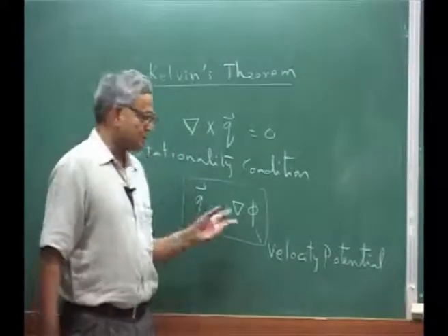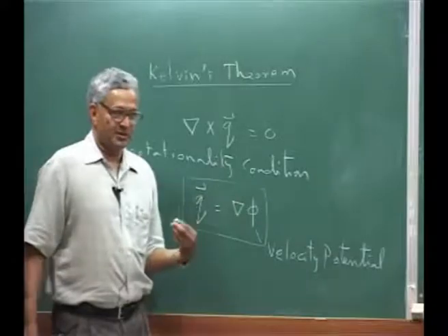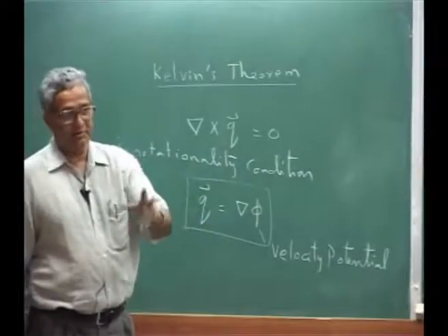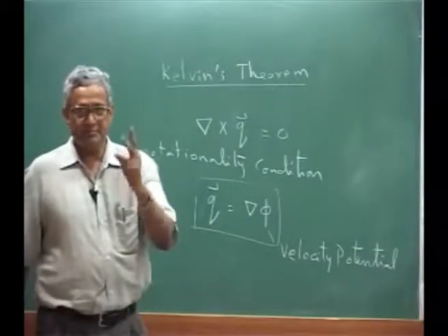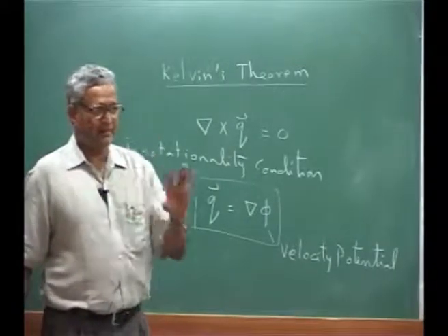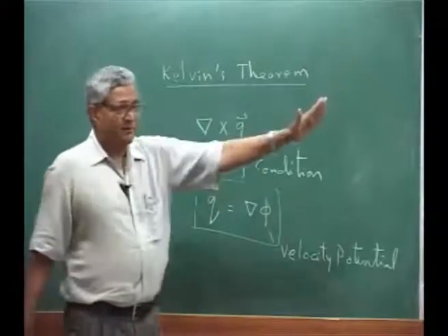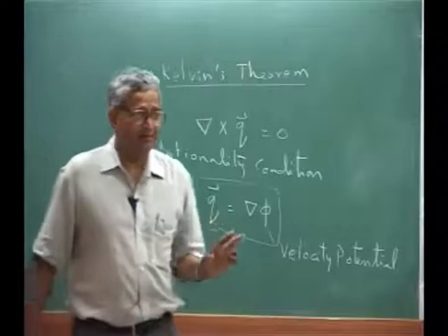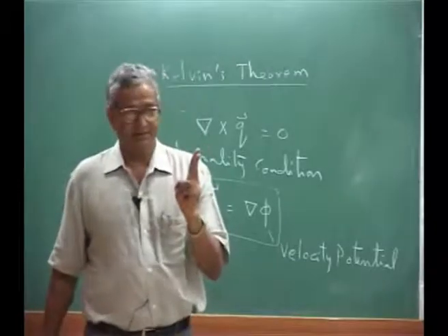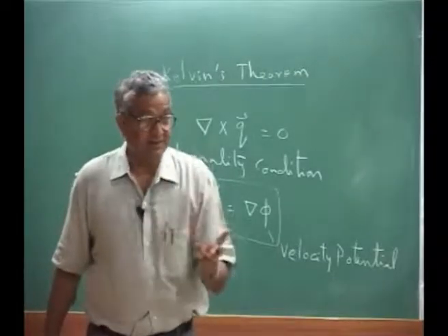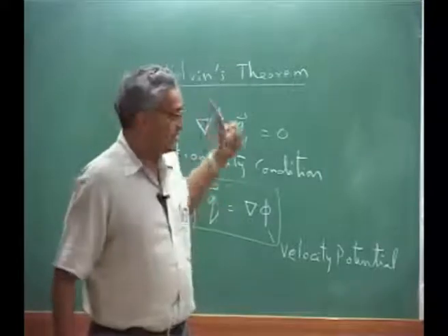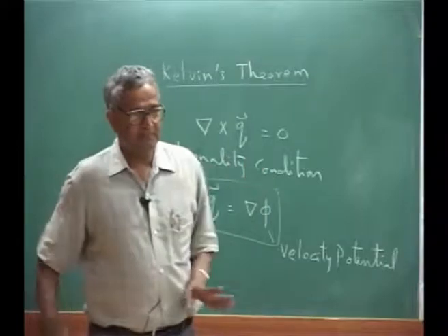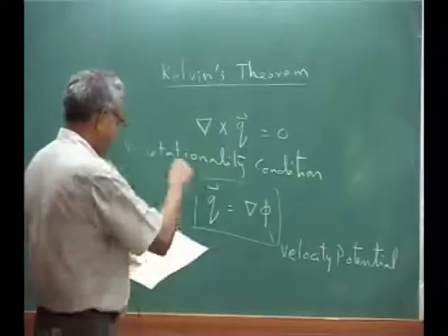But in that process, the speed of sound comes in, which means you should have another equation for the speed of sound. So we will have 2 variables and 2 equations. That's all. Your full potential flow theory is represented by 2 equations, whether it is steady or unsteady, because we are deriving the unsteady equation. You will find that these 2 are solved. Now we will get that equation.